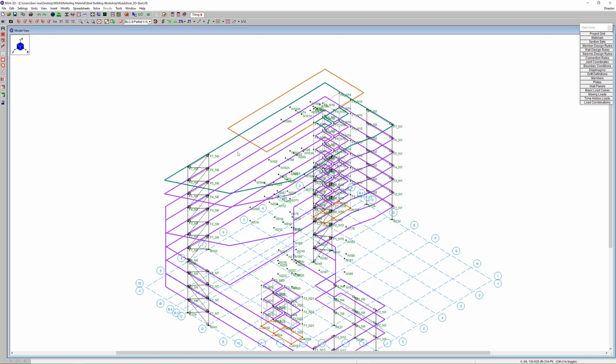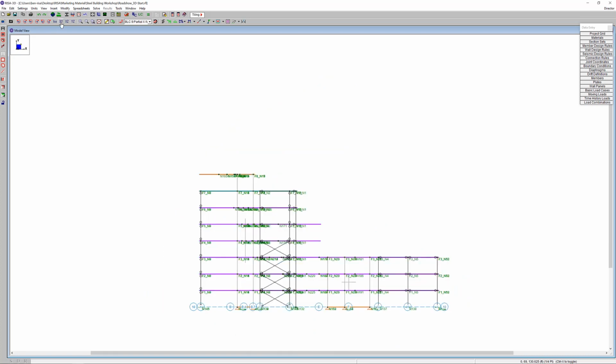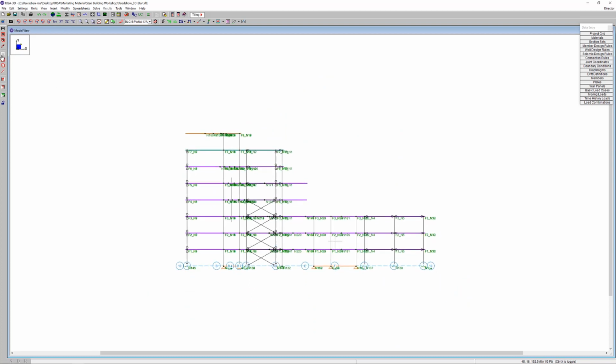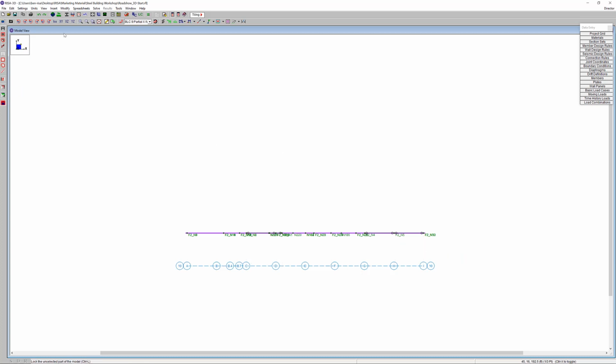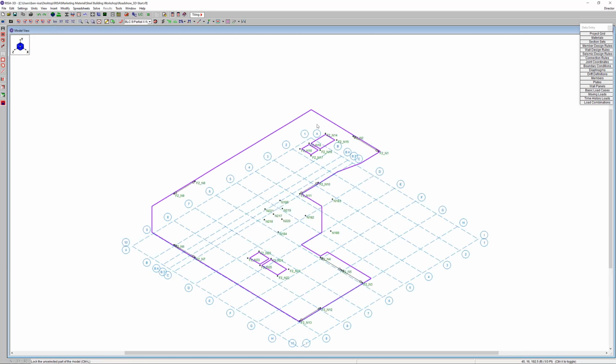So I'm going to go ahead and take a side view here, and I'm going to deselect everything and then only select level 2. So I just want to see the results on level 2. So I'll go ahead and lock that level and show an ISO. And so in seeing this, we can then go ahead and turn on some results. So let's go ahead and turn on the visibility of results. And again, we can start to see these nodes being used for different load applications.